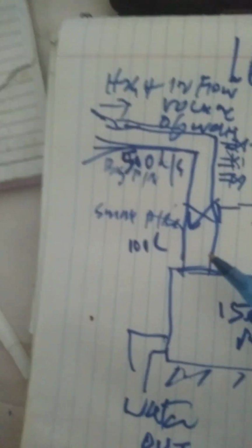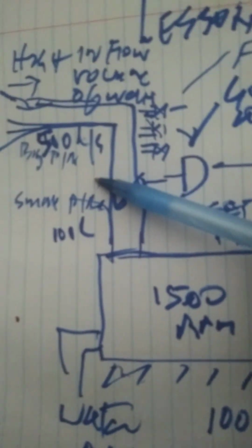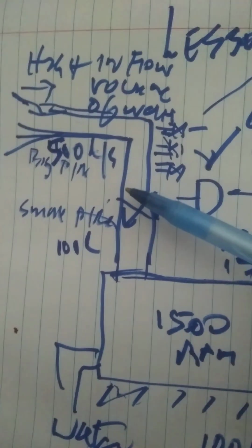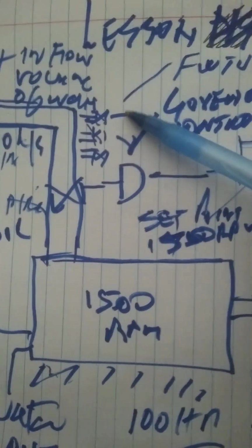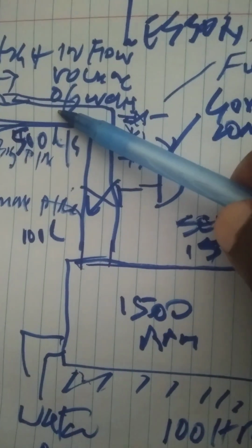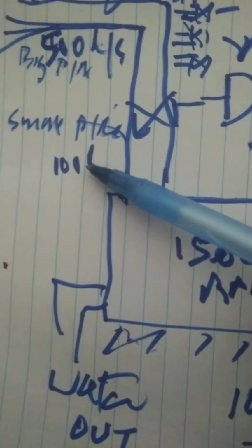Now, suppose you have a big flow of water coming in, for example 500 liters. Suppose the turbine uses 100 liters per second out of that 500, so you have excess water. Why? Because down the line you may be building another powerhouse, 100 liters per second, 100 liters per second, 100 liters per second. You have excess water, but this turbine will take only 100 liters per second.